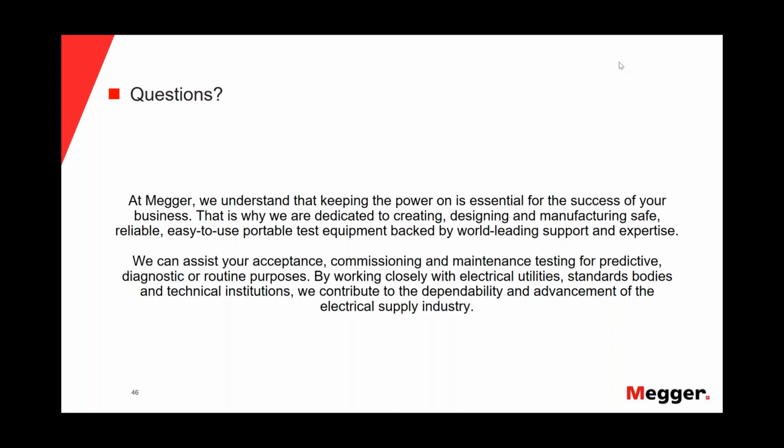Well, it depends how the cable was stored. For instance, if it was under the shadow, the temperature conditions, etc. But I would say that maybe the jacket, the first test I will do is to test the jacket of the cable, and then I will do a commissioning test, a commissioning VLF test.